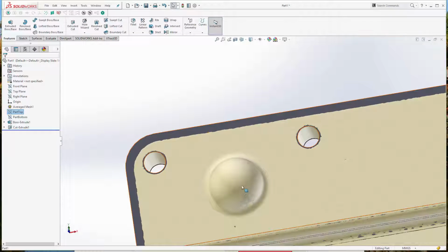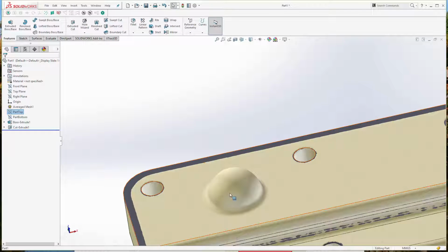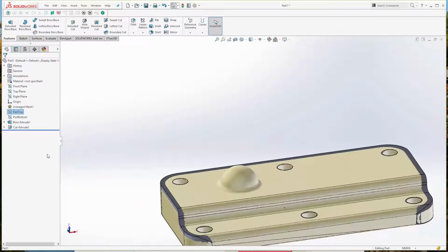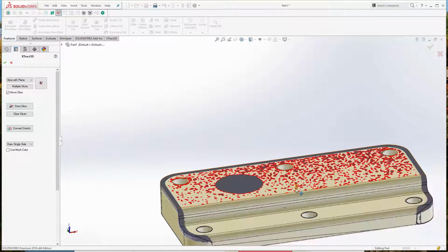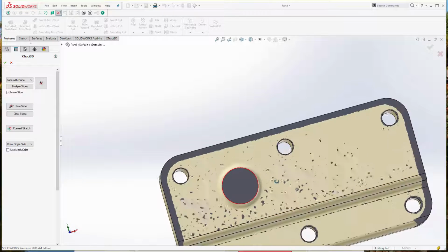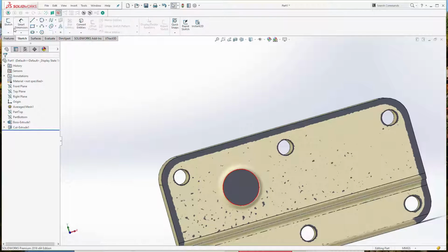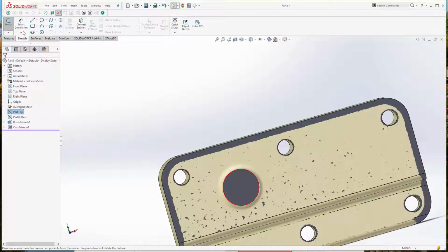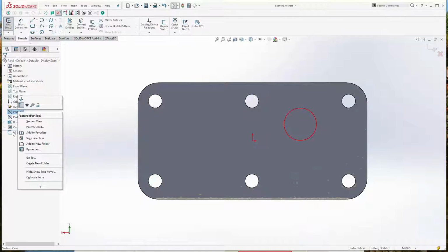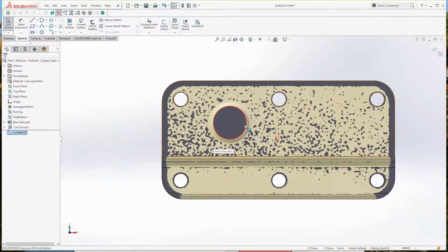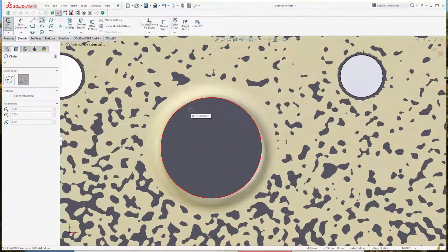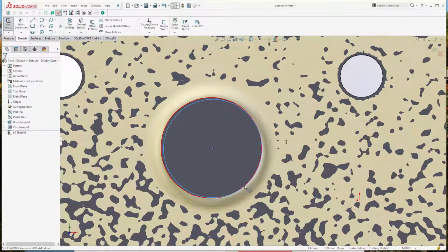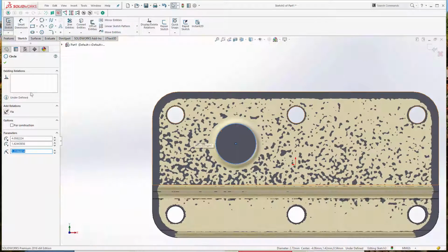What I'll do is extract the center axis from this, and then take that center axis and do a revolve, which is pretty straightforward. The way I'm going to do that is I'm just going to take the top part, slice it, move it up a bit, and create a circle right there. So from the part top, I'm going to start a new sketch from this side of it. And what I'll do is create a circle. There we go, take the circle, fit it in.